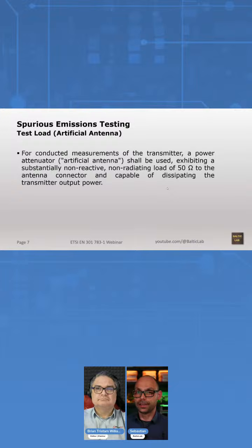The power handling, I often see that people measure a device that puts out up to 100 watts of power and have a 100-watt dummy load. It's not a good idea because that's a maximum limit, and the dummy load will heat up. And while it heats up, it will, of course, change its characteristics. So make sure you have plenty of headroom. Like for these less than 10-watt transmitters, I always use a 100-watt dummy load.